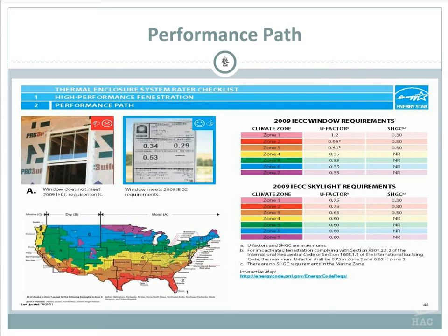A single wall skylight probably has a U value of 1.15. A double wall skylight, or a double glazed skylight, is going to have a 0.70. So if you're looking for something that's going to have to be a 0.60, you're going to have to go with a double insulated window or skylight.